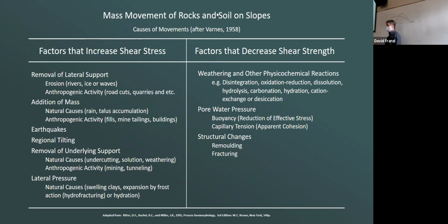You said that it kind of like slides along the plane on the bottom, right? Oh, no, that's the Morgenstern-Price. That's the non-circular slip. Okay. Yeah, and so if you have good subsurface information and you know that there's a stratigraphy there, right? Then you say, well, I'm not going to use a circular slip because, you know, you got this and then this.